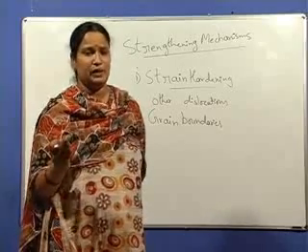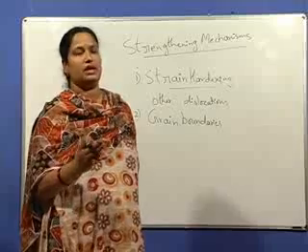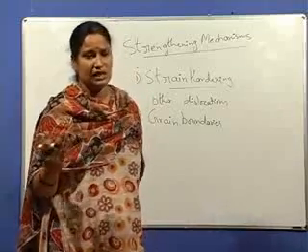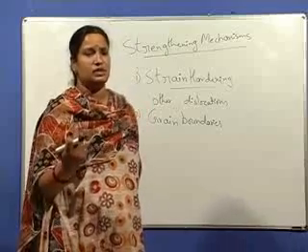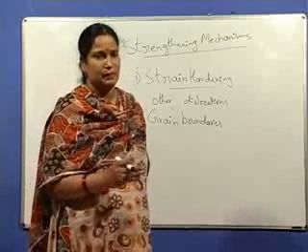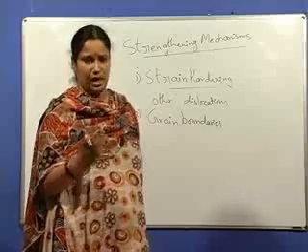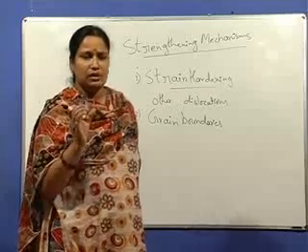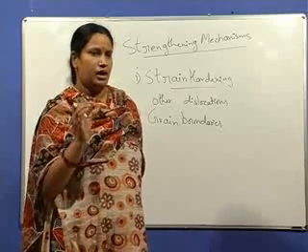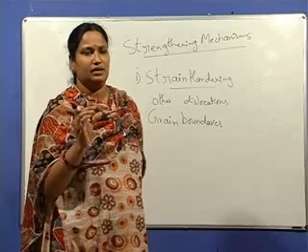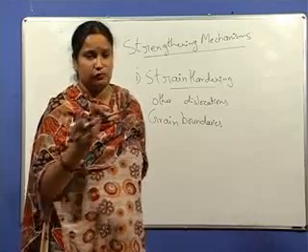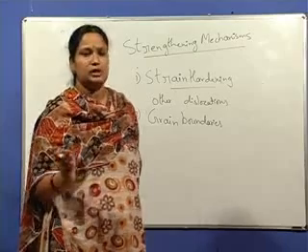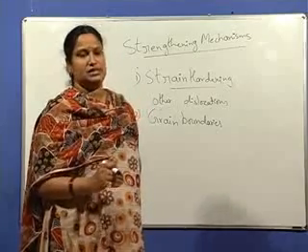And the equicohesive temperature, where the strength of the grain and grain boundary are the same, beyond which grains are stronger and grain boundaries are weaker. And below the equicohesive temperature, grain boundaries are stronger and the grain interior is weaker. And the smaller the grain, or the larger the grain boundary area, the higher is the density of geometric dislocations. So all these were discussed under grain boundaries.